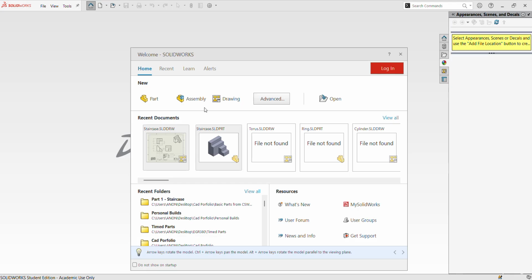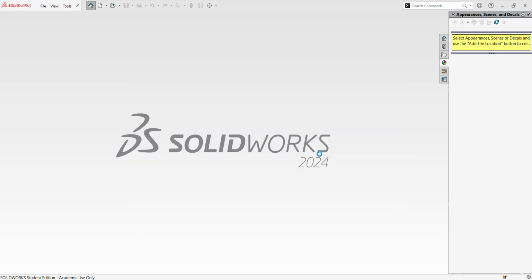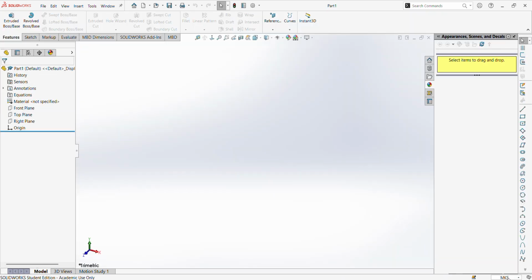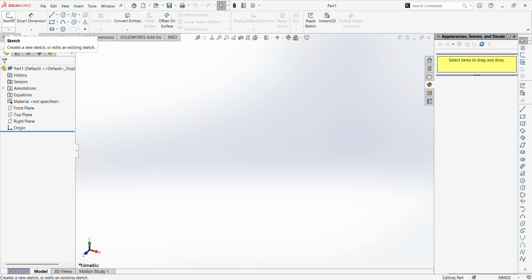I'm not going to go in depth and tell you how to get SolidWorks or download it. That you can figure out yourself. This is basically how to use it. Down here, you're always going to pick in the very beginning what your dimension measurements are. So we're going to be in millimeters because that's what our drawing called for, MMGS. And I made that drawing, and I'm going to make all these, pull them from books and things and ideas, and this one's just an idea.